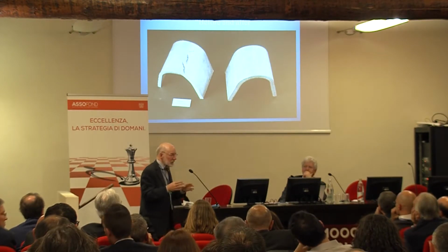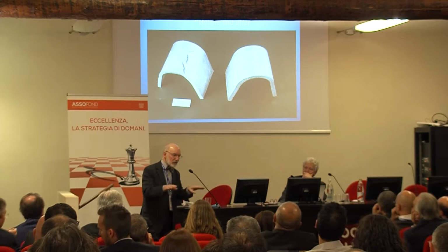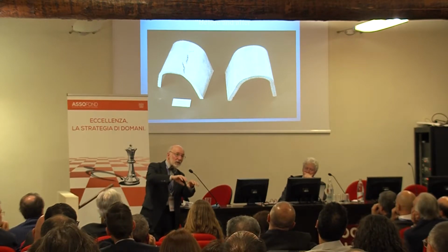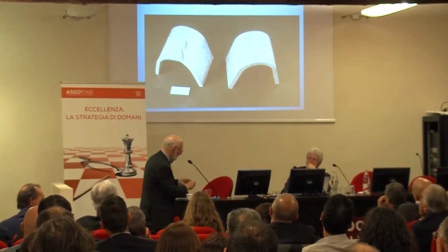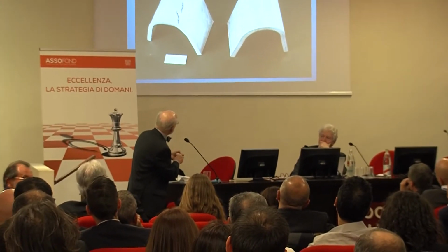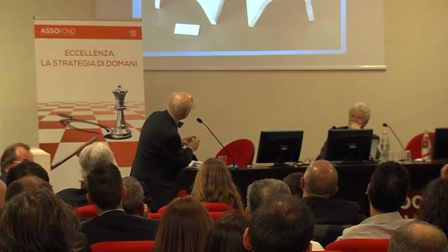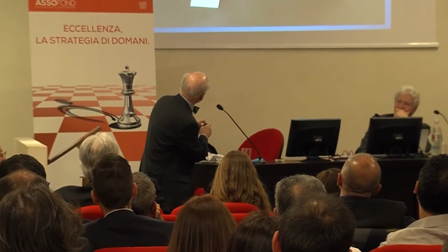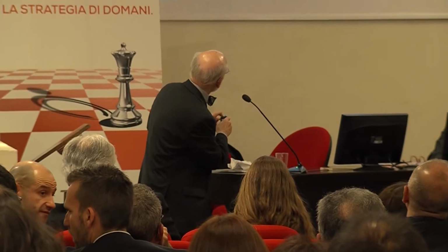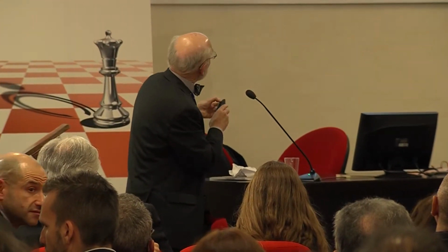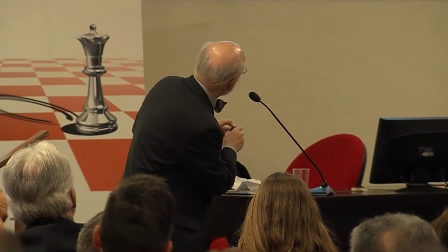This was just a couple of castings, which we did a 3-point bend. And what you can see, this is a casting with no defects, but this is a casting with huge cracks which have opened up. The important thing to see about these cracks is that they're not along the center of the axis.